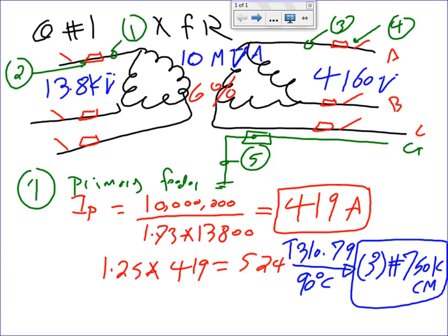Now Ryan might check for us if Southwire makes them. We might have to move to a different format just because they don't make a multi-conductor. That's a big conductor, 3 conductors in one big cable, 750 each. I don't know if they make them. What do you do if they don't? Then you go to a different table or different configuration that allows you to run one cable per duct, or a single conductor cable. So let me just go quick here, guys, and see if we might have an issue here. The conductor is too big.